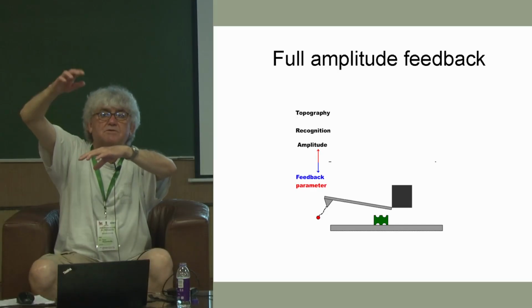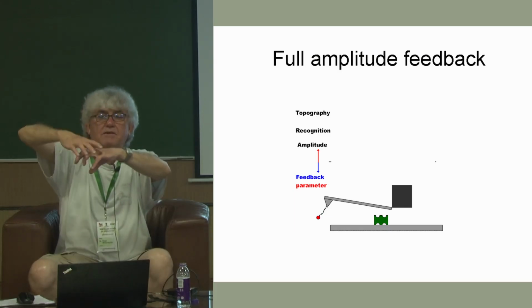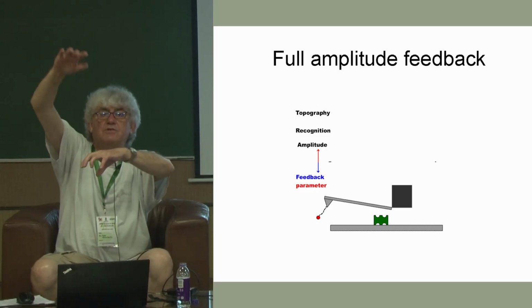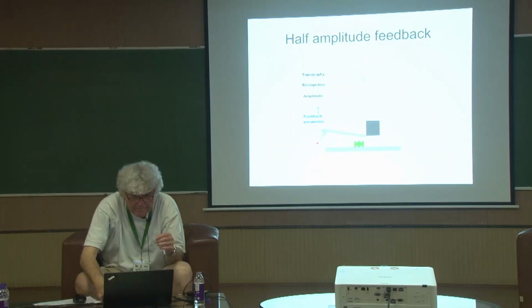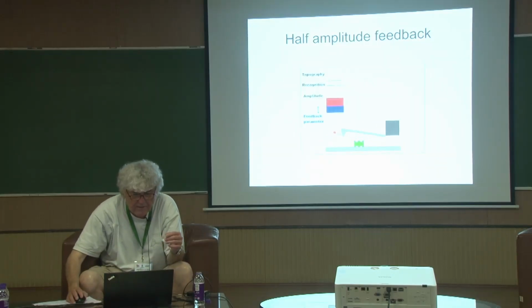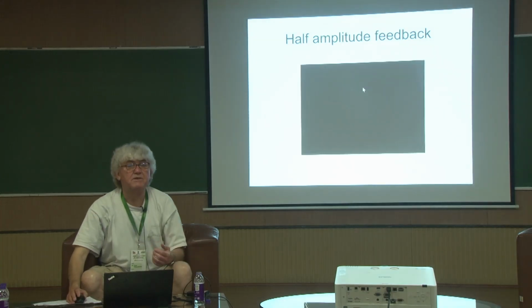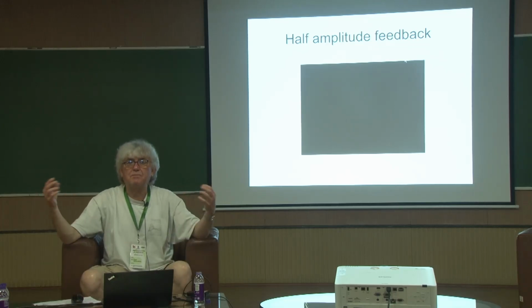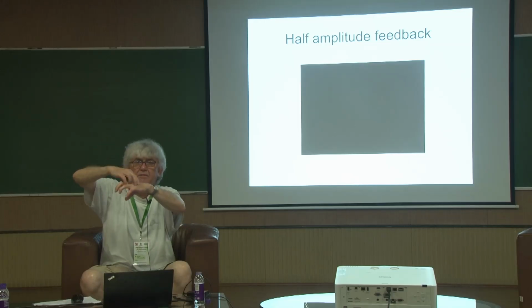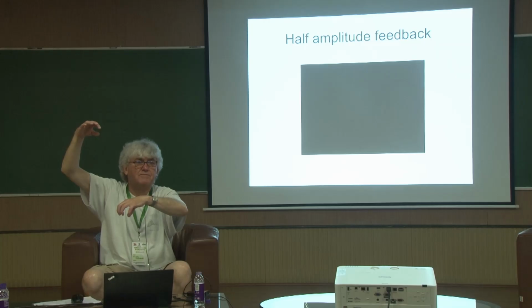That also reduces the amplitude, so we overestimate this amplitude reduction, and this is why the feedback goes too far up. So this is why we servo with the half amplitude, just with the downstrokes. If we servo with the downstroke, we get the right height, but also a recognition signal. Basically, it is much better to run the feedback loop just with the downstrokes and not with the whole amplitude.